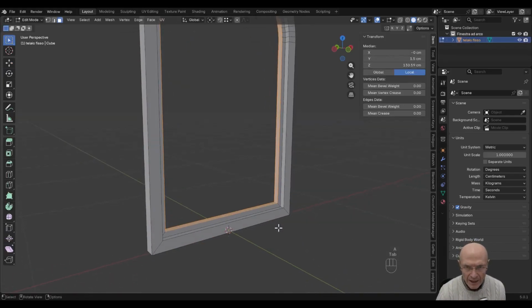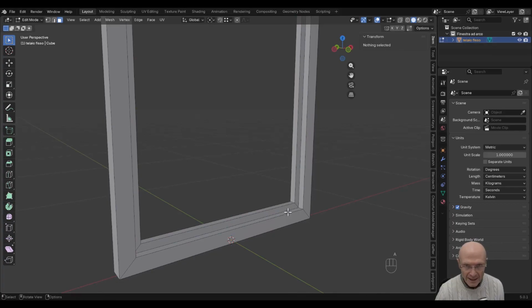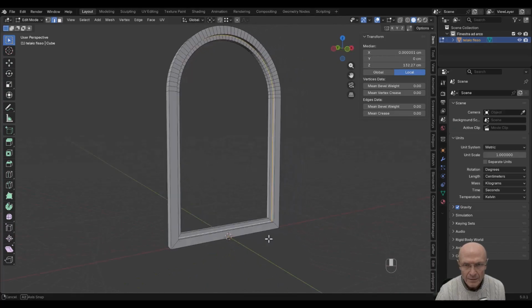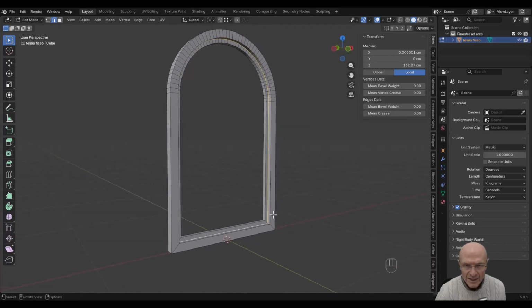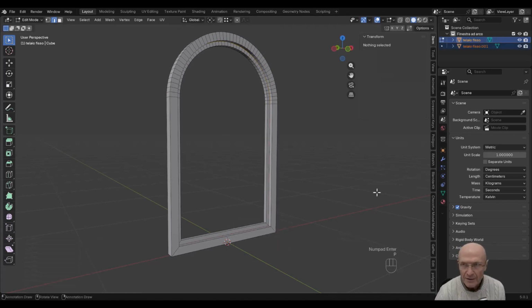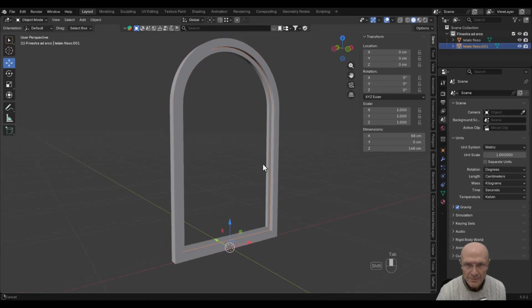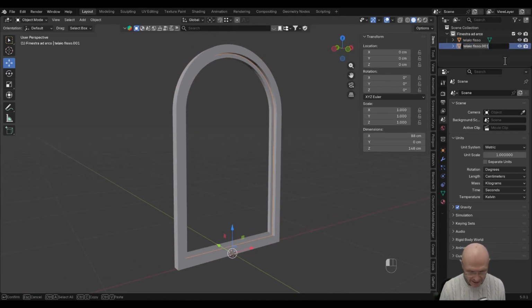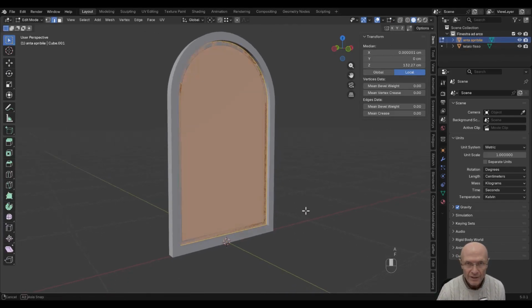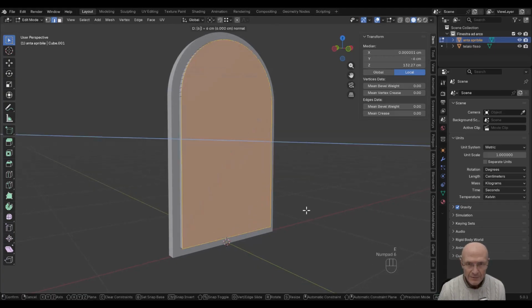Now let's see how to create the arch, the window, the opening part. Let's go into Edge Selection mode and then perform a ring selection on the edges. On this line, along this perimeter. Shift D, Enter, P, Selection. Back to Object mode, let's select this part and call it Opening Sash. Edit mode, select all, F to fill the geometry and E for extrusion. 6 centimeters.